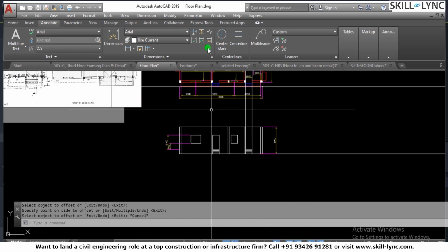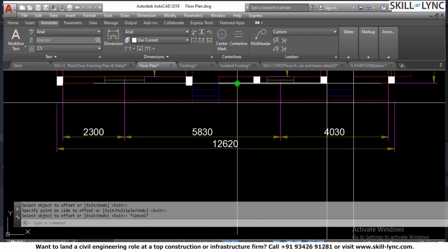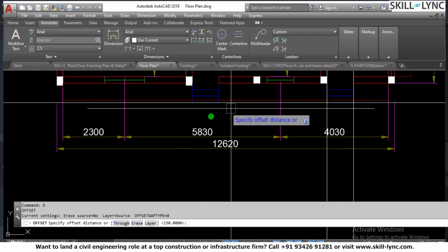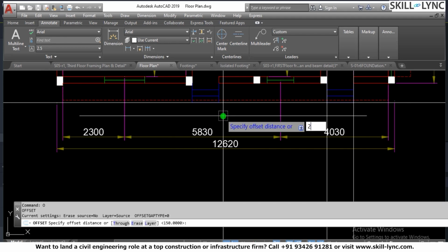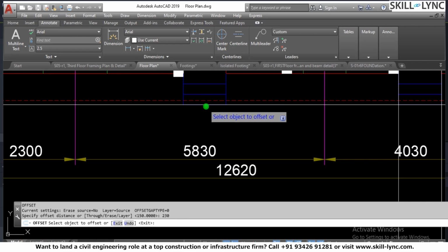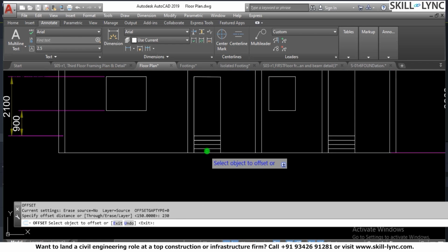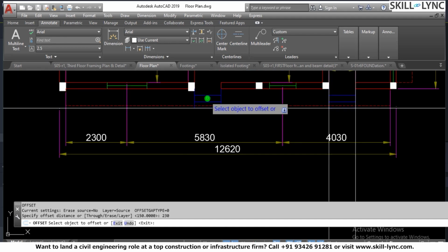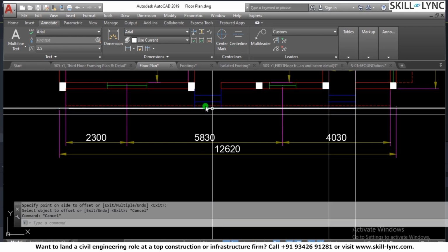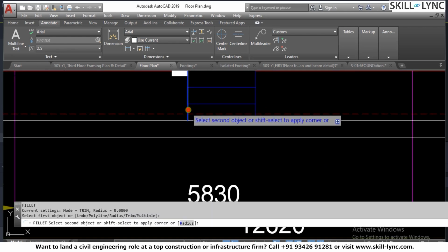Now you have to look into the plan. The plan is having 3 risers. So you have to increase one riser because now the plinth level is 600. So let's say in the plan, I would like to make a change. So the tread is 230 mm. So here I go with the number of risers, you're having 1, 2, 3, and 4. So in the fourth riser, you are basically going inside. So here you have 3 risers, so you can increase one, and always you can go for a fillet.